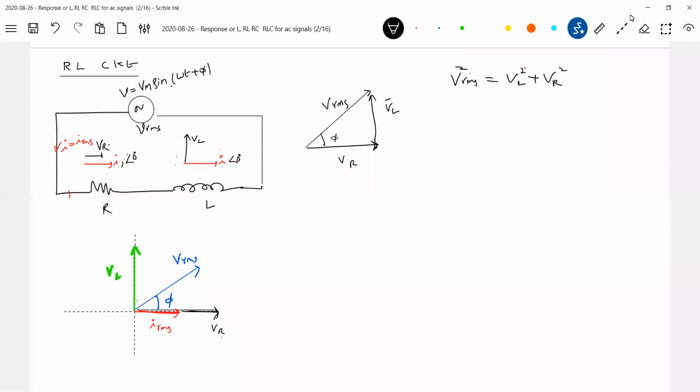In an AC circuit, vector sum of voltages has to be taken in a series circuit. In a parallel circuit, vector sum of currents should be taken. Write that on sticky notes. See it daily, 1 time, 2 times, 3 times, 100 times, 1000 times, 1 crore times. Daily you recite this: vector sum of voltages in series, vector sum of currents in parallel circuit. Finish all. Rest all is mathematics.